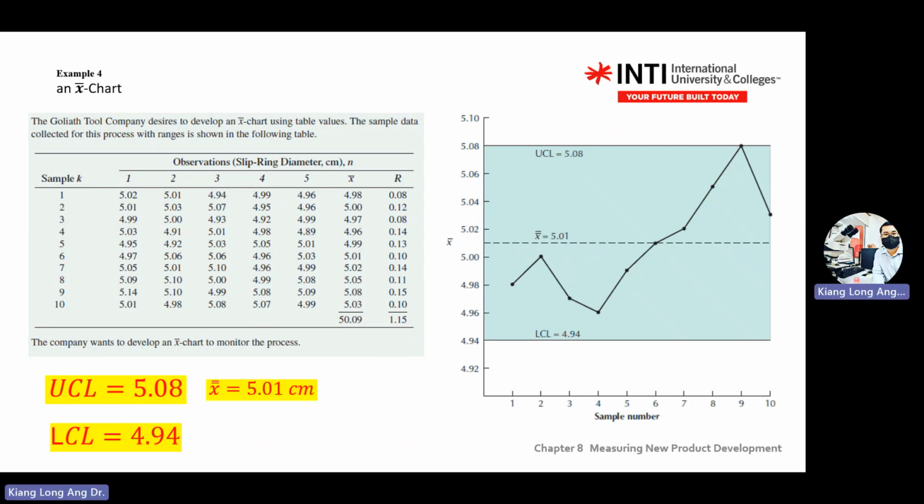However, when you are measuring sample 4 until sample 9, there is an uptrend towards ULC, but it dropped back again. Okay, so again, the mean chart is a very small sample. So what you do is you continue. If you're not confident about this chart, you run the process one more time by collecting the same 10 samples.